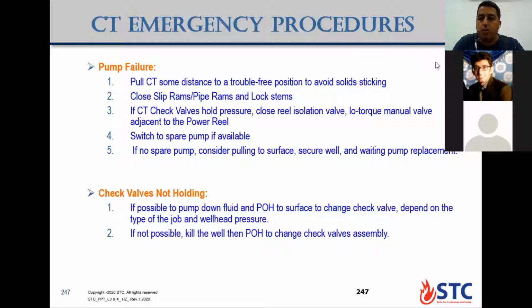Secure the well and wait for the pump replacement. After the pump is replaced, you will resume your operation, run to bottom and continue. This procedure is just a guideline or recommendation. It can vary a little bit, as I said in the beginning, from policy to policy, according to the depths, also for the coiled tubing, the tool string, which is the position inside the wellbore, and also depends on the pressure for the wellhead.